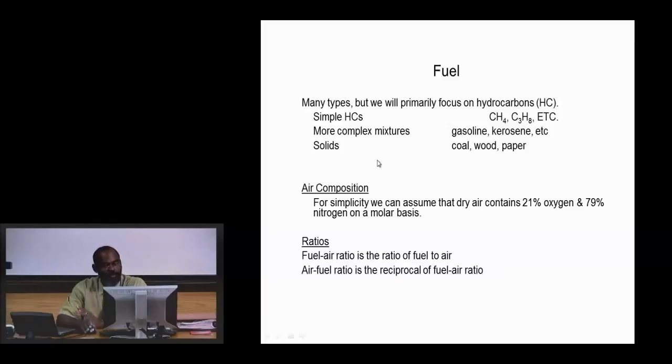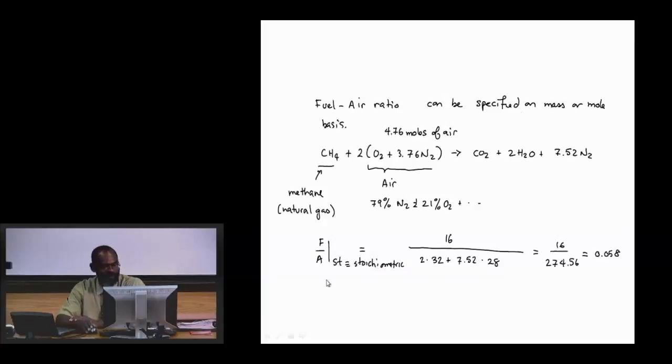So in developing all of this, though, we need to understand some basic issues in terms of stoichiometry and the characterization of these gas systems. We model air as 21% oxygen, 79% nitrogen. So we understand there are other things in air, but for the purposes of combustion or fire, this is adequate in terms of modeling the impact of air on the combustion evolution. And we'll talk quickly about the different types of ratios one uses to describe combustion systems, the fuel-air ratio and the air-fuel ratio.